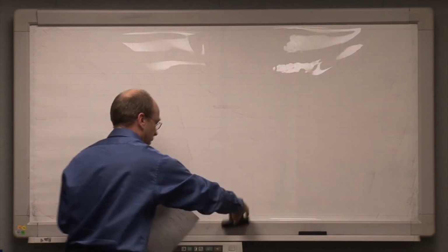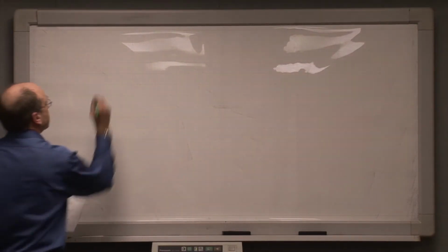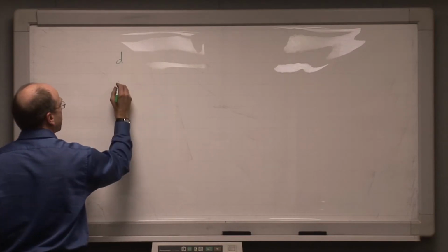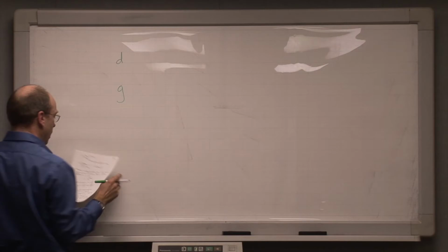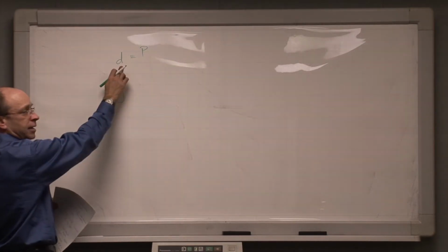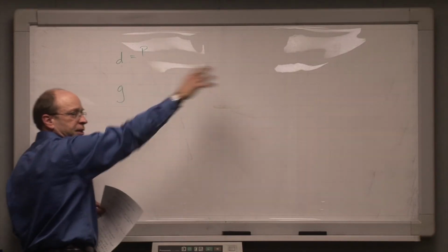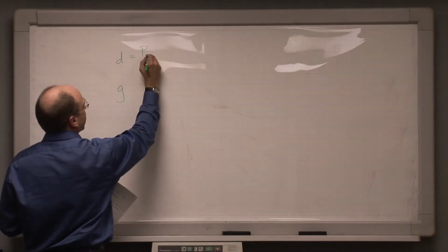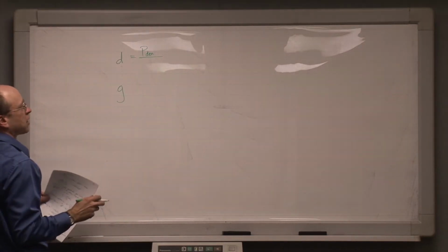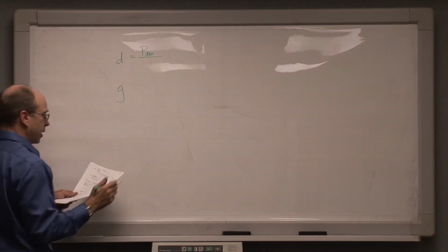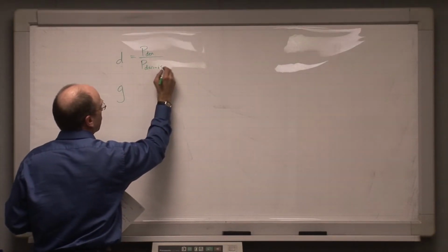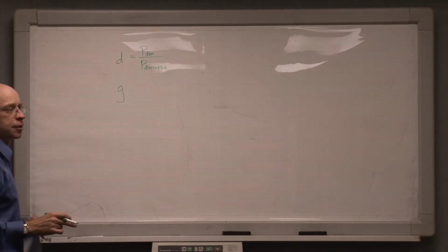Now, believe it or not, we're actually close to being done. I want to talk about directivity, which I'll write as D, versus gain, G. If we're talking about beaming energy into space, receiving energy from space, the directivity of an antenna is going to be equal to the power density in some lobe or beam coming out of that antenna divided by the power density that would have been produced had we been using an isotropic antenna.